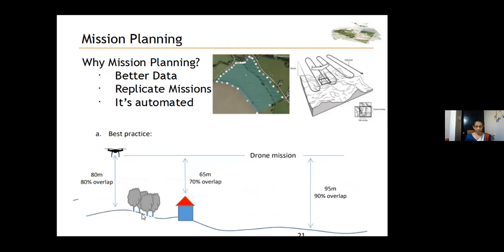Here you can see what happens if you change your starting point to these locations with 80% overlap. When it comes to these locations, you can see the overlap is increased to 90%. It increased, but it does not matter because you have enough overlap. You can get common detail based on this overlap area. Of course, there are some problems with high overlap, such as battery problems, and it takes too much time. But we have the data, and we will not lose some of the information.